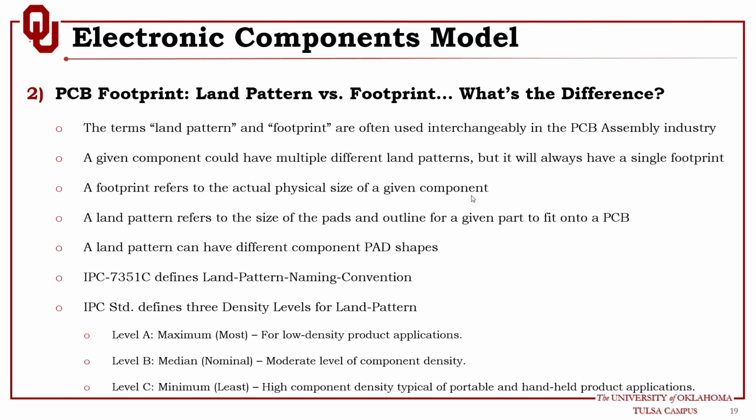Now the land pattern. We know that the footprint has one shape of the component, which is defined by the manufacturer of the chip. We cannot change that. But the land pattern could have different shapes, and we'll see examples in the next slide. Now, the naming convention for these land patterns or footprints when you design a library is defined in the IPC standard. The IPC is the Association Connecting Electronics Industries, a trade association whose aim is to standardize the assembly and production requirements of electronic equipment and assemblies. So when you design a library, you need to follow a specific standard if you want a standardized library that can be shared among different entities.